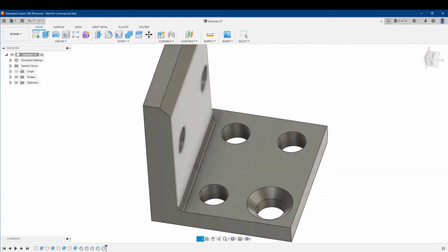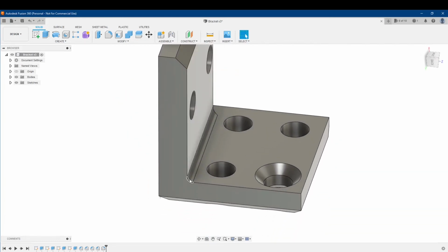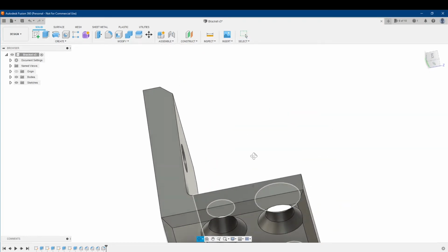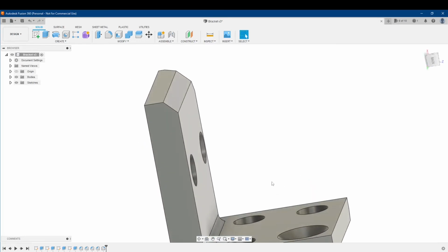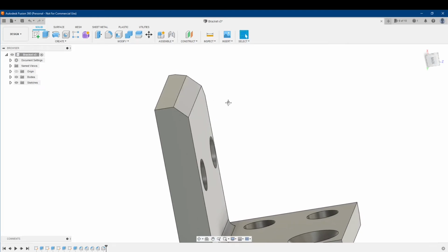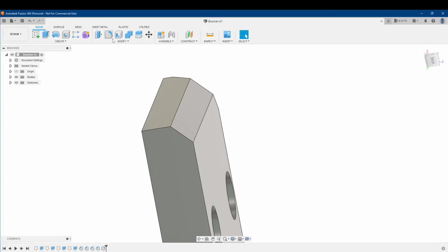But when I'm printing parts too, and I really want to take advantage of a fillet, that's for stress purposes. They're good for that. Chamfers I usually use solely for artistic purposes. If I really need a slanted edge for something, I want to adjust the angle of it too. I really want a sloped edge or surface. I find chamfer really useful for that.